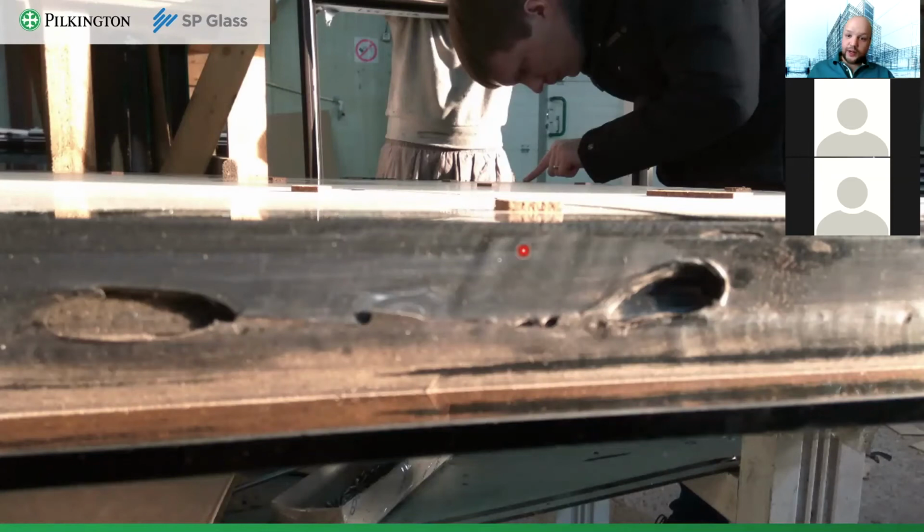Now on that picture, I will be showing you one of the defects which is critical on every secondary sealant. So please be careful to look for gaps and holes inside the sealing. It should not have them. Because in this place, your IG unit can fail during its lifetime.